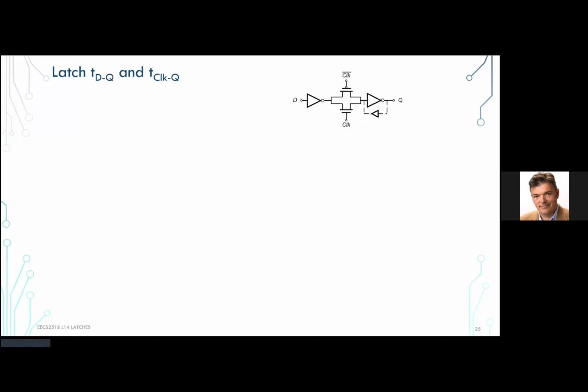So if I have a 2-stage network, this should drive some kind of fan out for optimality. Otherwise, you throw a latch in there, and your timing optimization, your synthesis tool, is going to always throw a buffer after it. You try to optimize that. But for now, let's assume that the fan out is 1.